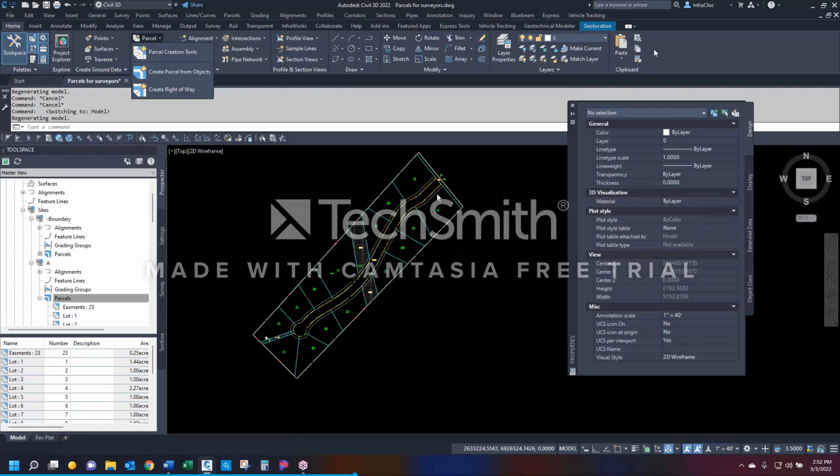Do you want a corner clip or not? When you do that, it will make this interior parcel for you. You don't have to necessarily start off with your own that you made from a polyline. You can start off with an alignment. The problem is getting it to make it with the cul-de-sac. Have fun with that. It's just easier to offset the alignment 30 feet each side and put in the cul-de-sac properly and blend the line work yourself and then do this. Much easier than struggling through it.